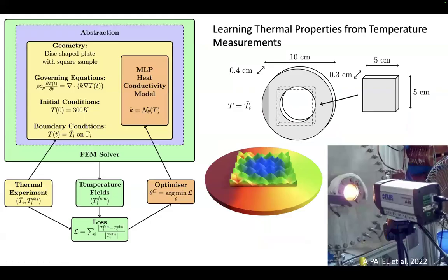And then finally, very quickly, you might say, well, you're training a model just with 2D examples. What about more complicated equations or more time-dependent equations in 3D? Can you use this kind of simulation to train your model? And the answer is yes. For instance, here I want to learn a nonlinear conductivity of this particular material, which is a 3D plate with this very complicated geometry, and it's actually a two-body problem. So I have a copper plate with known thermal properties, and this complex shaped plate with unknown nonlinear thermal properties that I want to learn.